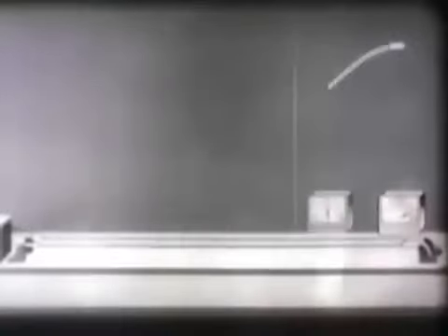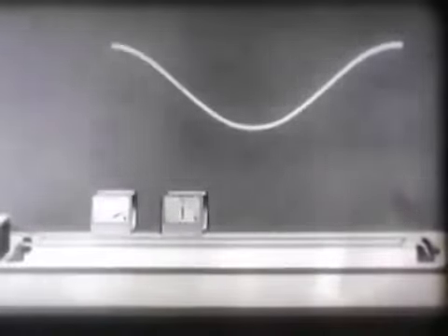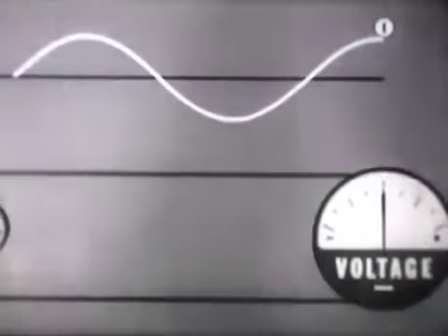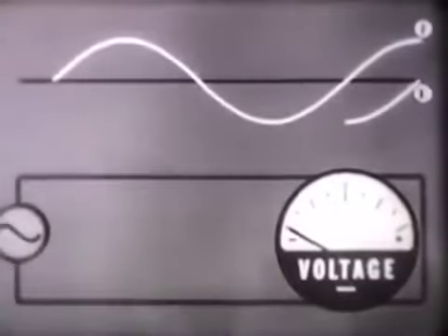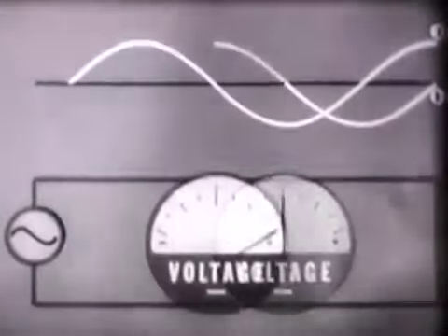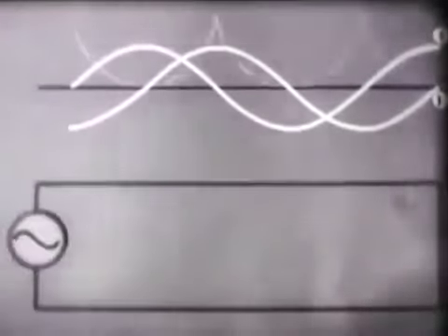The standing wave of current on the transmission line can be plotted as easily as the voltage. It is a closed circuit. At the shorted end, the current reading is maximum for the line. A half wavelength down, the current is again maximum, and so on to complete the standing wave of current. The voltage at the closed end of the line is, of course, at minimum value. 1/4 wavelength down, the voltage reaches its peak, and so on to complete the standing wave of voltage. Impedance is minimum at the shorted end of the line.